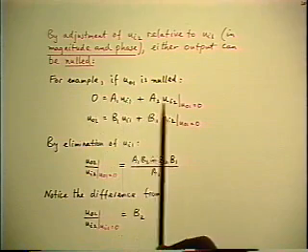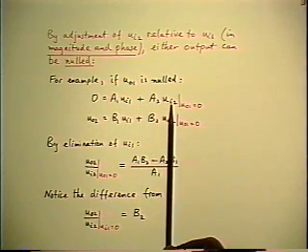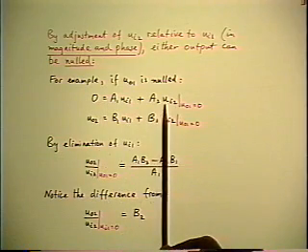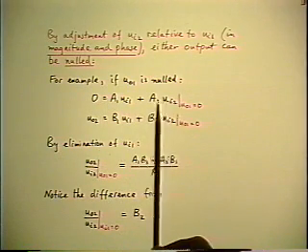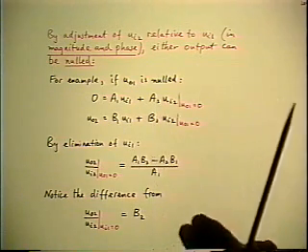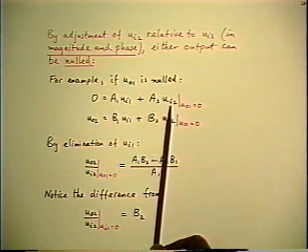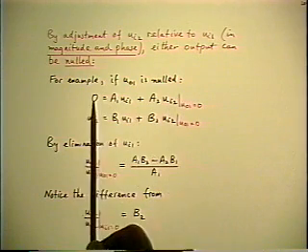Notice that what you do in that case is that you fix the relative values of those two inputs. Because if you solve that equation, you end up with a ratio of the two inputs, which is a unique value. It's equal to the negative of the ratio of the coefficients, which is a fixed value. That is the ratio of inputs that you have to apply in order to null that output.